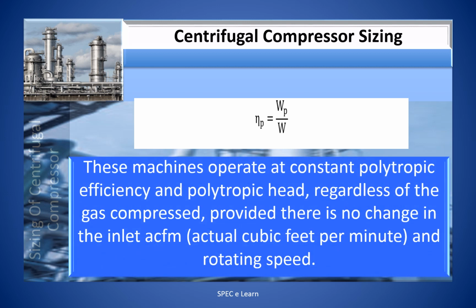Centrifugal compressors operate at constant polytropic efficiency and polytropic head regardless of the gas compressed, provided there is no change in the inlet volumetric flow rate.